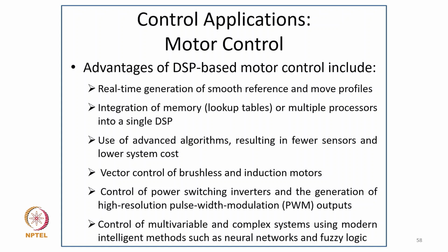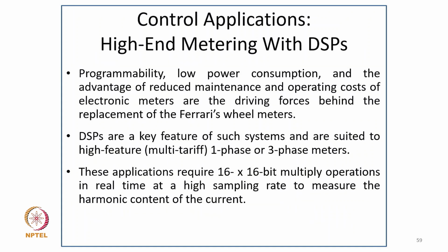So coming to the advantages of DSP-based motor control, they include the real-time generation of smooth reference and move profiles, integration of memory like lookup tables and multiple processors into a single DSP, and use of advanced algorithms resulting in fewer sensors and lower system cost, like vector control of brushless and induction motors, control of power switching inverters, the generation of high resolution pulse width modulation output, and control of multivariable and complex systems using modern intelligent methods such as neural networks and fuzzy logic.